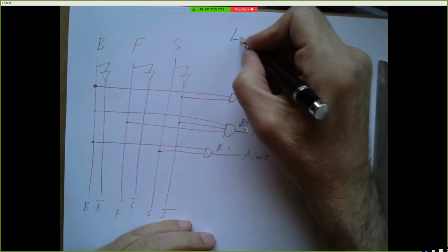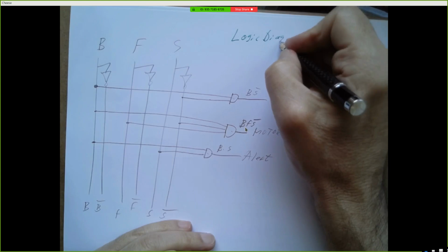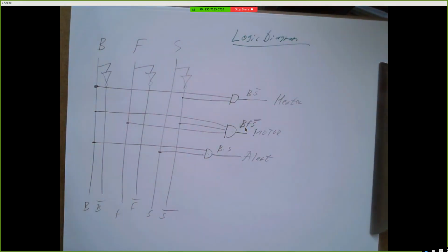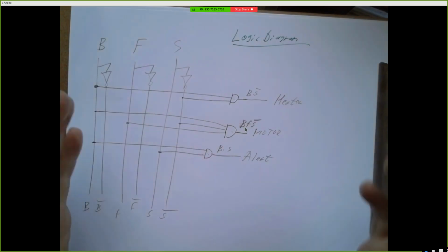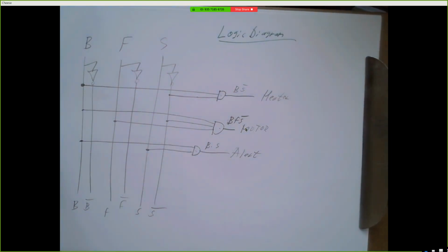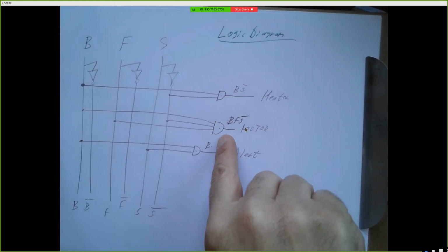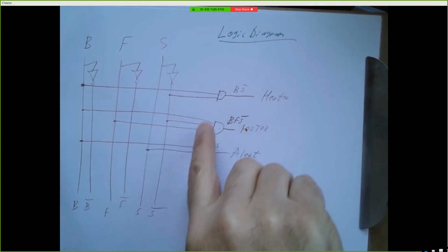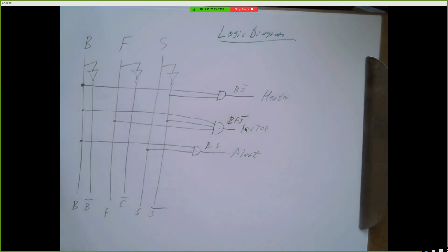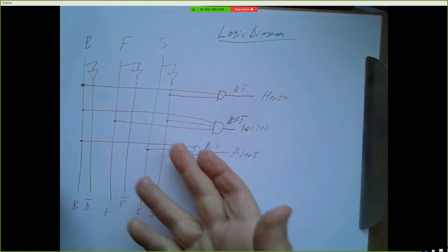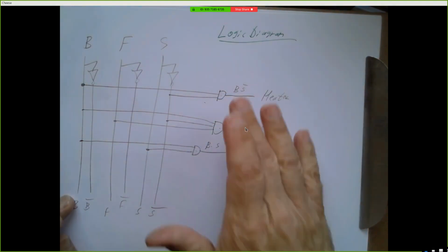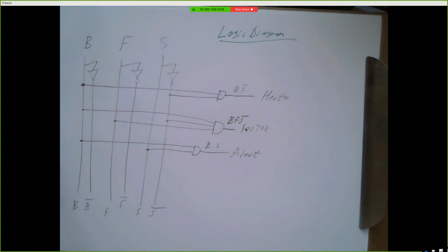Okay, so let's call this a logic diagram. It's still not a complete wiring diagram. If someone handed you this and asked you to build the circuit in Tinkercad, you would have to do a lot of online work. You would have to figure out which gates correspond to these. You'd have to look up their pin numbers. You'd have to decide which pins to use for each of these. You'd have to wire up switches and so on. So this is a logic diagram, right? It's written in this universal language of logic symbols, inverters, AND gates, and so on. But it's not quite a wiring diagram.